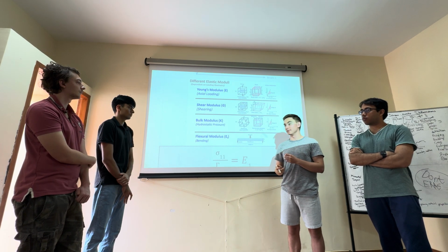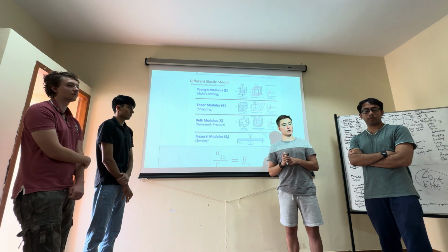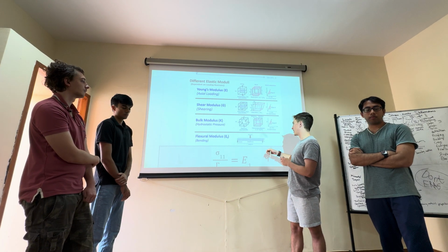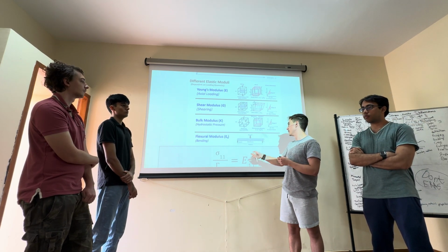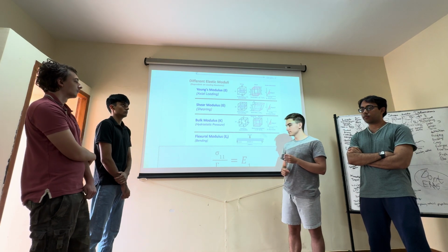since we didn't talk so much about flexing of beams. But if you're looking more towards civil engineering applications, that would be an important one. If you're talking about bridges or anything else that uses a beam, say you have your supports here and a person or a car or some sort of load weighing down in the middle, that's going to cause a flexing of that beam that you want to minimize.